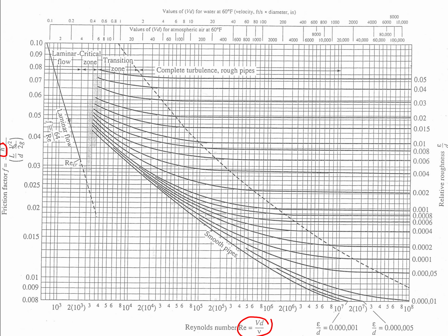So we see that the friction head loss, normalized by some flow and pipe parameters, would indeed depend on the velocity in the pipe, the diameter of the pipe, as well as the viscosity and density of the flow that is being pumped.